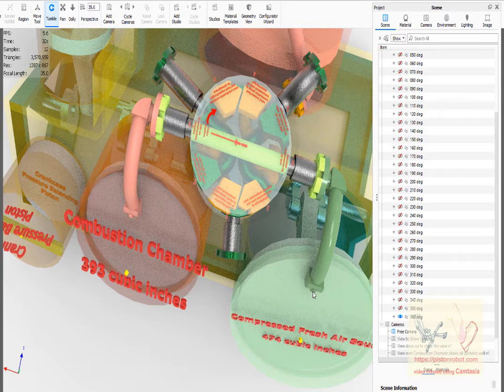You can see that everything I'm explaining is being explained at zero motion speed, because it's nearly impossible to explain it otherwise. And you have to, in your mind, understand that the engine is actually moving. So this compressed air piston is going to come up, and as it gets to top dead center, this alignment is going to turn into place, so that this compressed air that was in this chamber and couldn't go anywhere now has a lined up tube so that it can go over into the combustion chamber, because prior to that it wasn't able to do that.